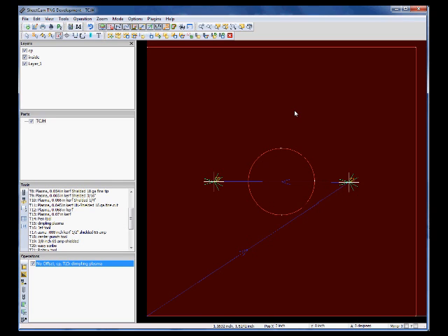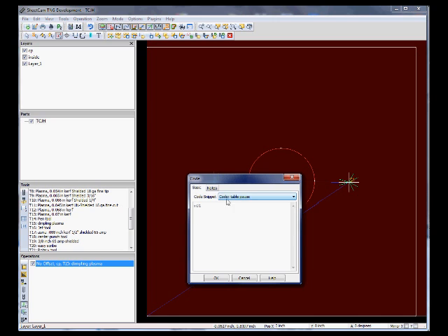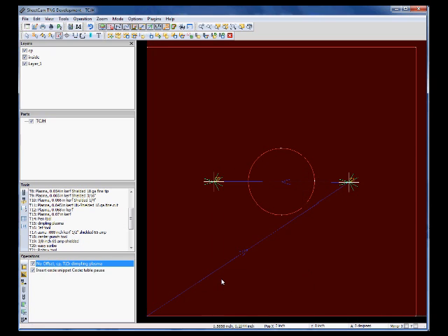Now, what I do, I have another code snippet that I generated, which is basically table pause. I want to pause before I go on to cut the other parts, because I want to change the amperage on my plasma. So table pause was the name of it, and it's an M01, which is a stop. So I click on this and it puts it here,